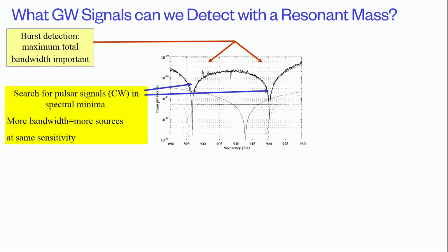And that's not even all of it, right? So one such measurement would take 200 milliseconds. But with the spectrum analyzer, there's statistical noise. So if you just took that one 200 millisecond noise plot, this curve would be very thick. There would be noise on the noise measurement. So to lower the noise on the noise measurement, you average the noise measurement for 50 or 100 averages. So then you end up measuring for 200 milliseconds times 50 or 100, depending on how many averages you did.